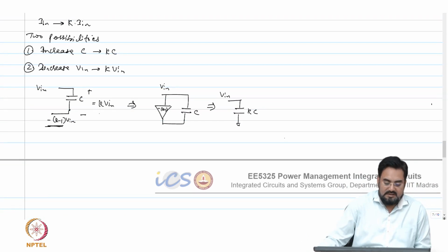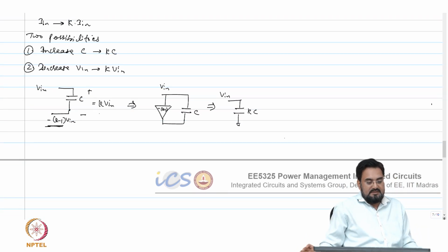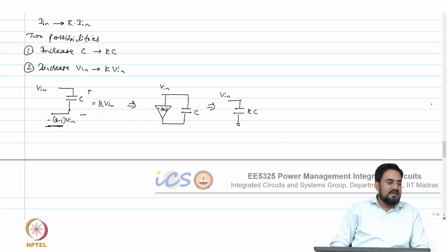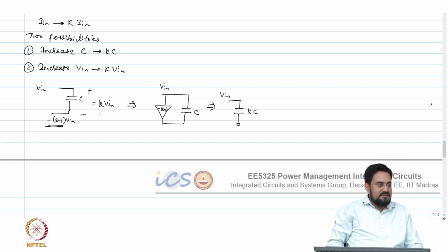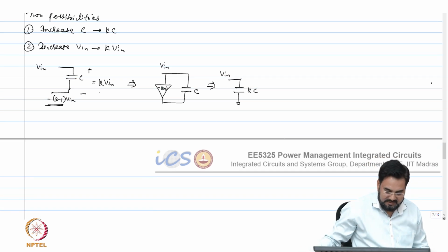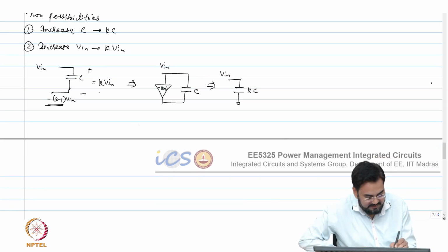Okay, so which means if you put the capacitor around an amplifier, the negative feedback, the capacitor looking at the input will be multiplied by 1 plus gain times. Okay, and if gain is very large, more than 100 or so, you can approximate, say, gain times. That's what is called Miller effect.